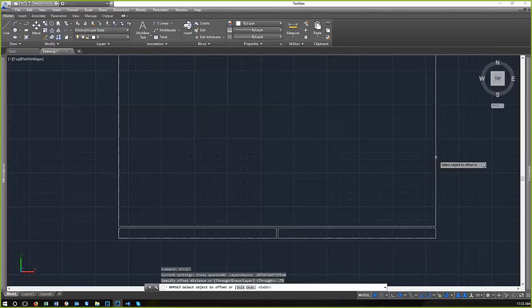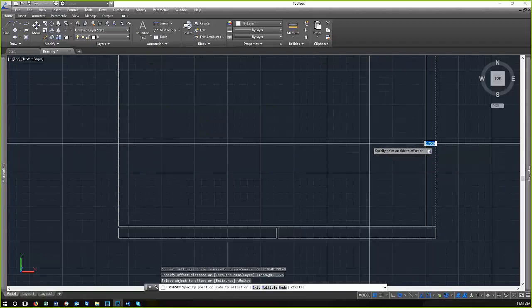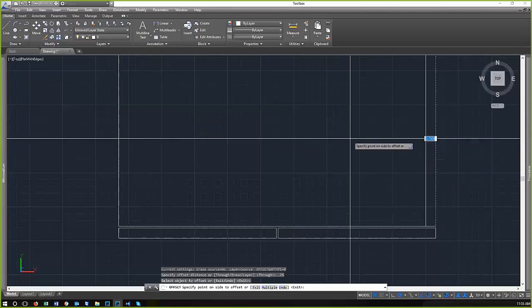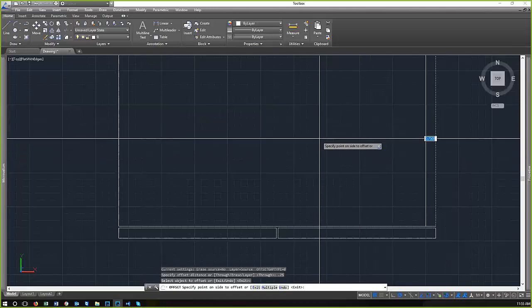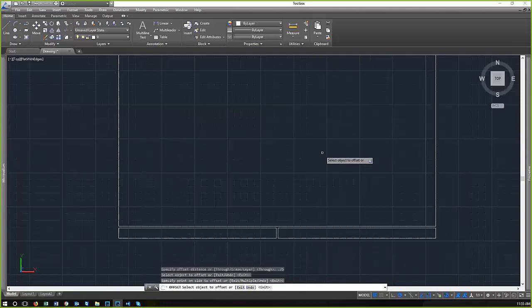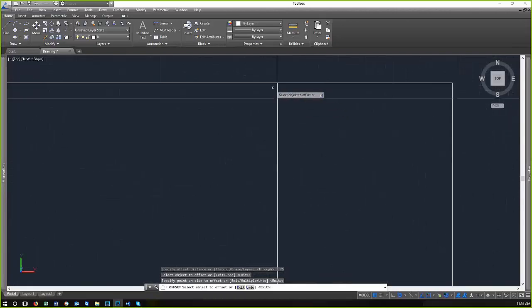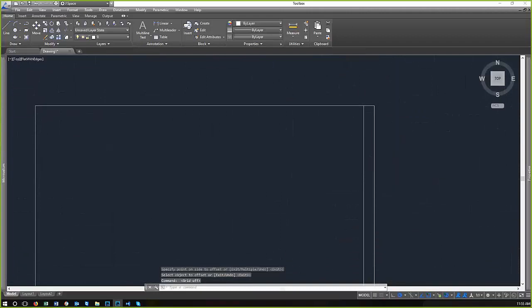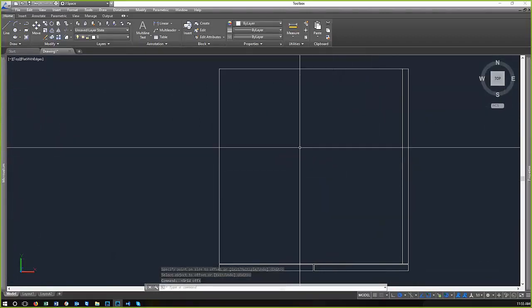and select your original lines. And then you're going to select which side you want to offset to. So it creates a parallel line in reference to your original line. So I'm going to offset 0.75 this direction. And it showed up, it's almost on top of that grid line. So here's a good reason to turn off that grid. So there you go. I got another line offset exactly 0.75.